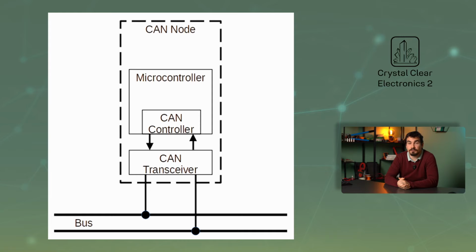Just from its name, it can be difficult to identify what CAN is, how it works, or what it is used for. That is why we are here. CAN is a multi-master protocol, so unlike in the general use of I2C and SPI, there is not a single master device and multiple slave devices, but all devices have equal status.